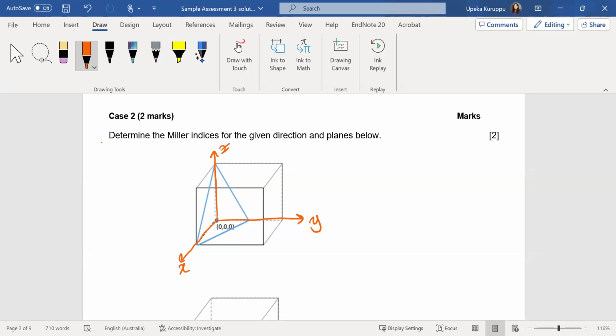So in case you want to change this one, if you want to make this X and this Y, then what should be the Z? Take your right hand and turn from X to Y. Before you were turning like this. Now you're turning like that. So if you want to put your axes like this, your Z should be downward.